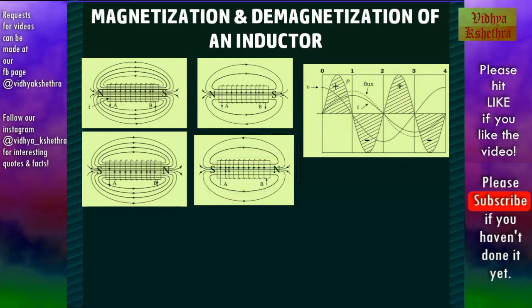Now from 3 to 4. In this stage, the voltage is positive and current is negative. Hence, the energy is given to the source from the inductor. And since the current goes on decreasing, the core gets demagnetized.